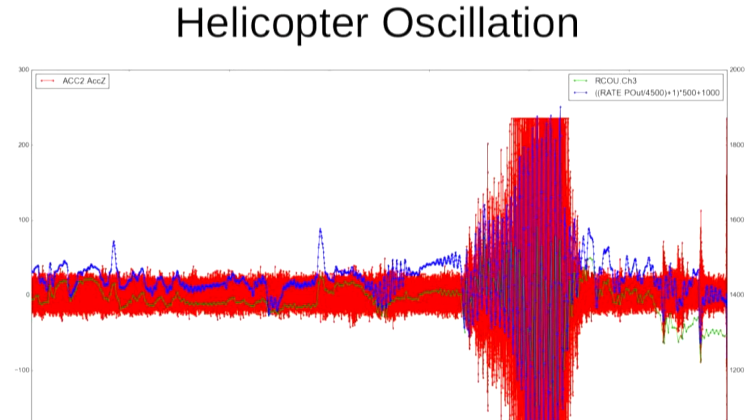What we're seeing here, now again the numbers might be a little bit small, so on the left-hand axis we're seeing the amplitude. The red line is the amplitude of the accelerometer, right? Just our vertical accelerometer, just one axis of it. And the scale there, the first number past the midpoint is 100 meters per second, so 10G. And you can see there that there's this band. On the left-hand side, it's flying beautifully, right? Really nice flight, beautifully stable, lovely helicopter.